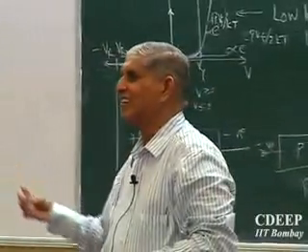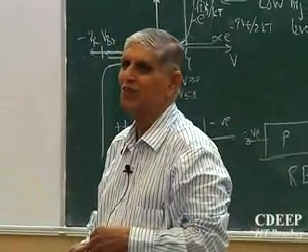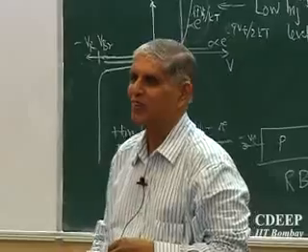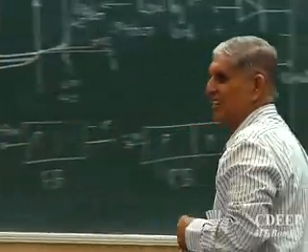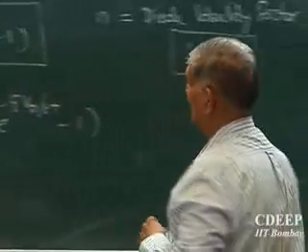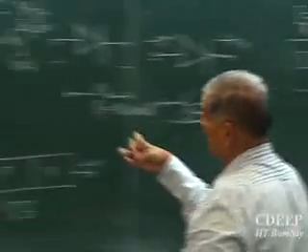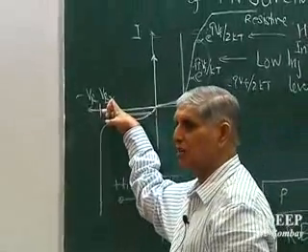It's called a power rectifier. All transmission systems will use converters; rectifier is named converter if you take a course in machines. Inverter, converter. Converting AC into DC is called converters. DC into AC is called inverters. Basically similar. There also we use a diode. Here also we use a diode. There we may use a modified diode which is called a silicon controlled rectifier, SCR. But they are still diodes.